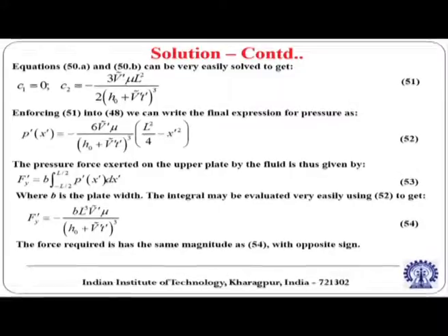At a very large height you will require basically no force to separate, but is it within the purview of lubrication theory? The answer is no, because when h becomes larger and larger, at infinite time it can become comparable to and even larger than the axial length scale L. Then lubrication theory will break down.